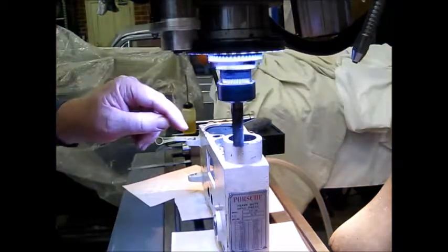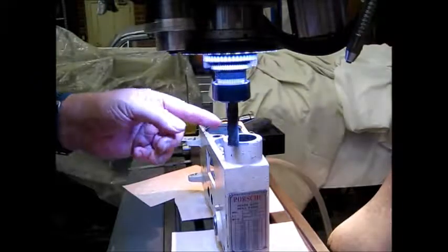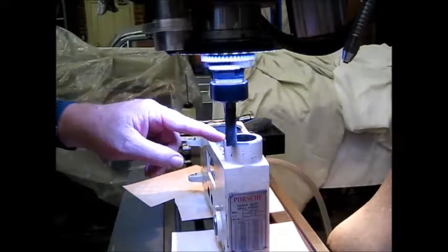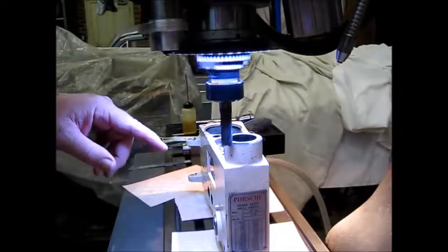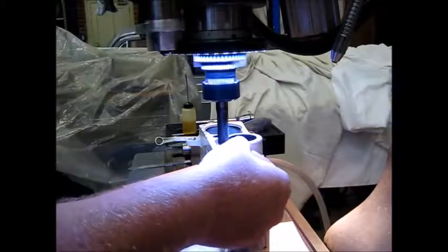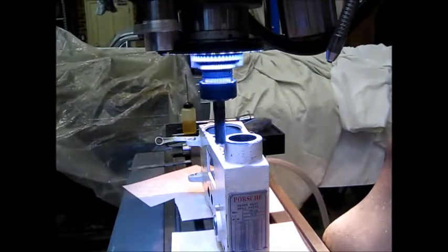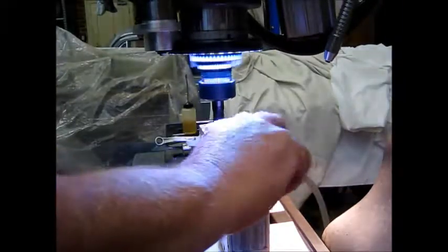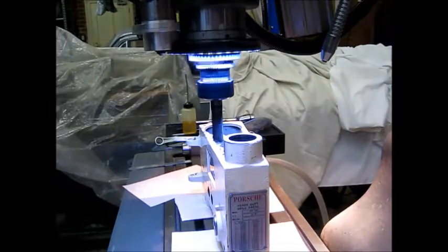As I mentioned, this is a 16mm tungsten end mill, four flute. We're going fairly slowly there. You can see taking less than 2mm cut, and already I can see we're running pretty parallel to the internal bore there.